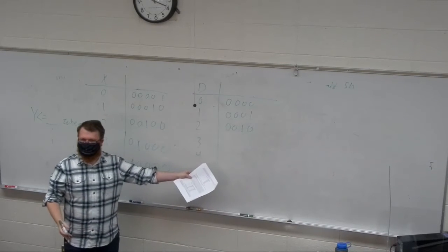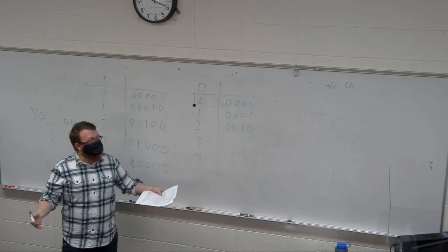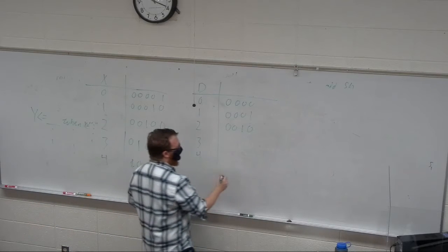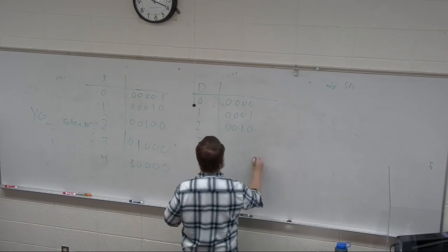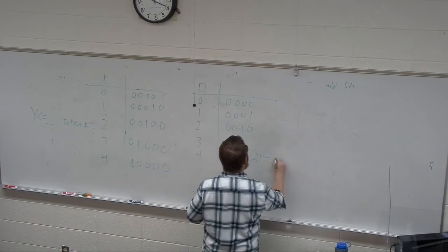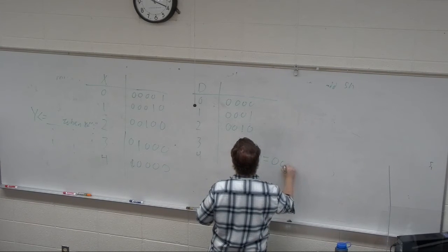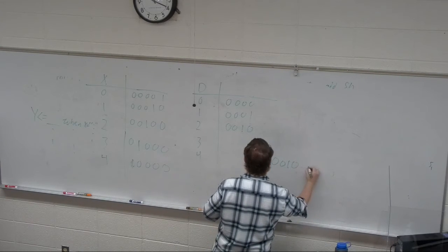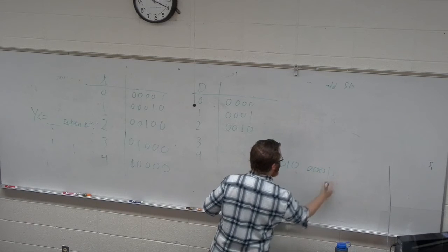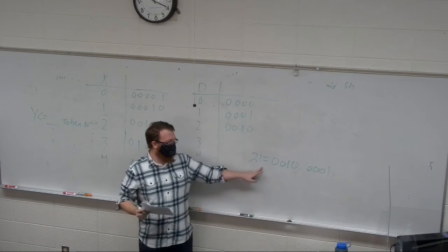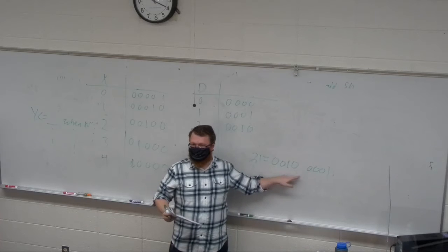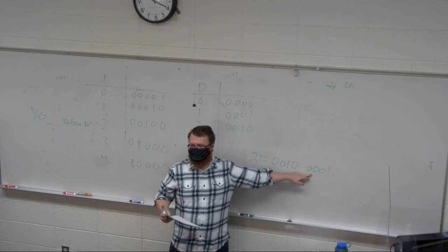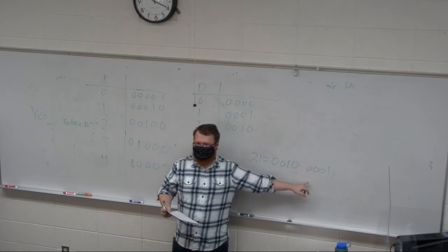It's just binary. But if I wanted to write 21, instead of figuring out what all of the binary is for 21, I would write 2 as 0010 and 1 as 0001, right? Wasteful. I don't need this many bits to represent 21, but it makes it really easy to deal with digits individually.